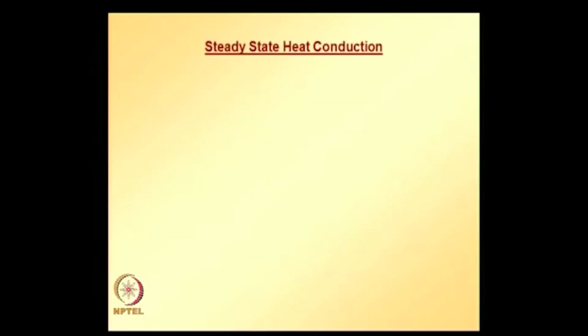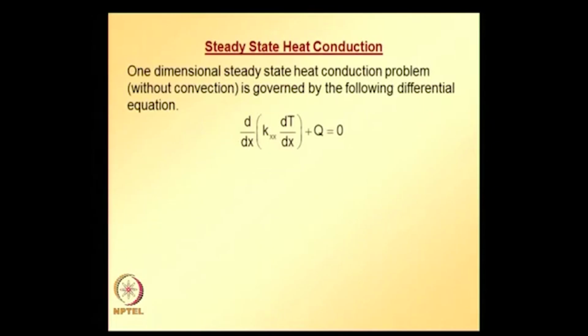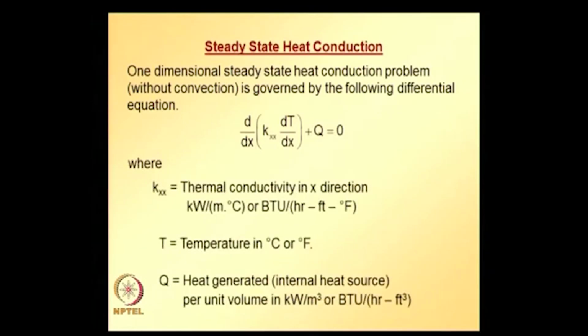So now let us look at the application, steady state heat conduction. The one dimensional steady state heat conduction problem without convection is governed by the following differential equation, where Kxx is thermal conductivity in x direction.